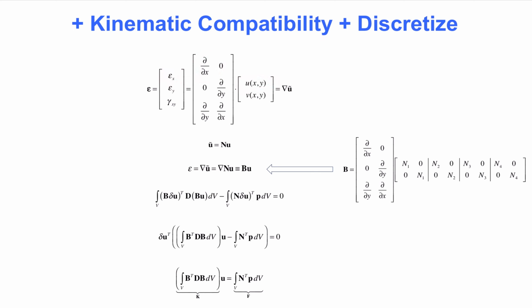However, those equations are now expressed in matrix form. The shear strain expression derived in the two-dimensional theory of elasticity says that gamma is the derivative of the displacement in the x direction with respect to y, plus the derivative of the displacement in the y direction with respect to x. Carefully note that we have introduced the symbol nabla to represent the matrix of differential operators.